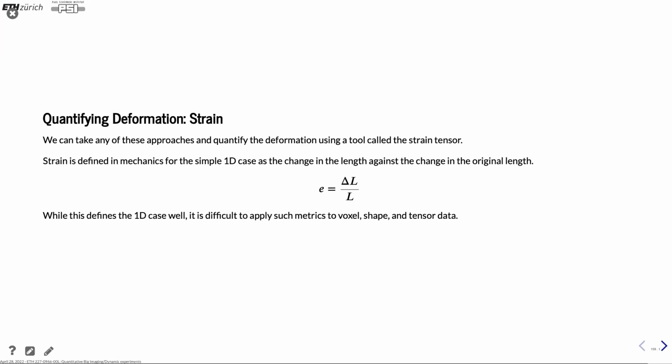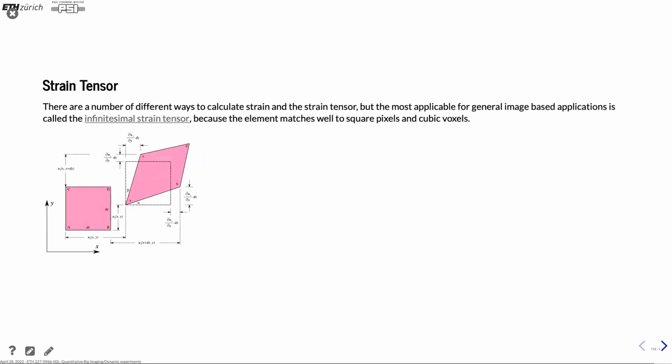And what we can do with the help of this is we can actually quantify the deformation in the sample working with a strain. So we want to look at the relative displacements within the image. And that can tell us then if we do some kind of pull or push test, how the object is changing over time in the images. And what we can get is the strain tensor, which tells us how the whole object is displaced.